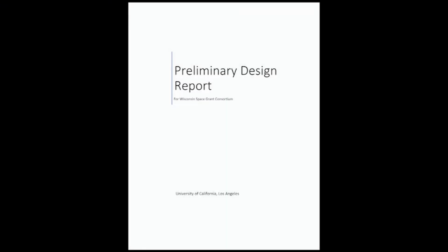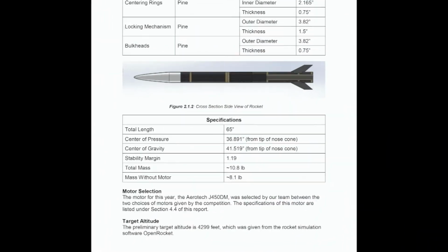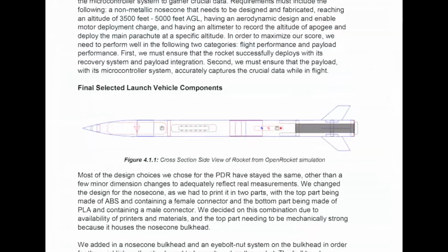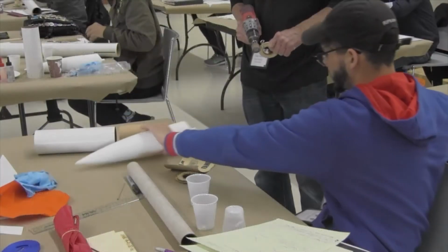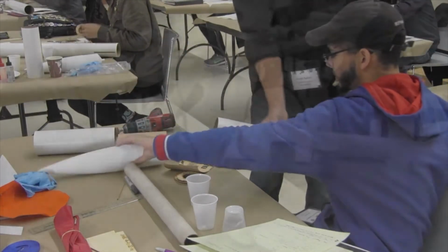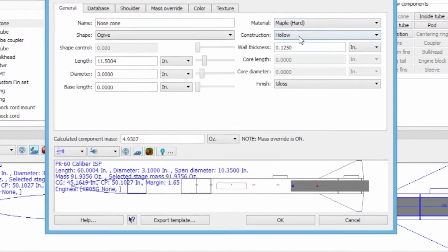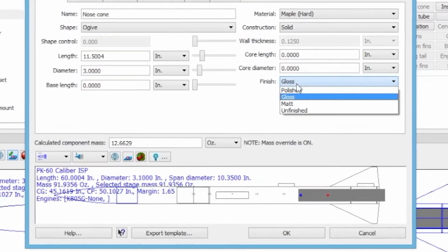In the proposal and preliminary phases of the First Nations launch, your team should run many simulations, examining as many kits as possible to determine the best kit-motor-parachute combination that will satisfy requirements. Once the kit arrives and the build progresses, keep in mind that modifications will be made in order to accommodate your challenge payload and solution. It is a good idea to regularly update the simulation to match your existing rocket, to ensure any changes will not violate vehicle performance requirements.